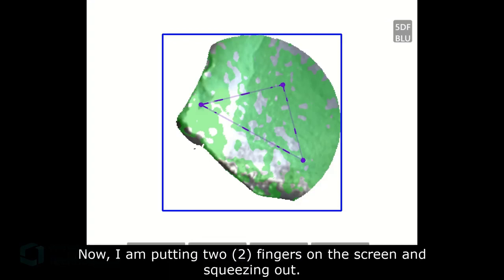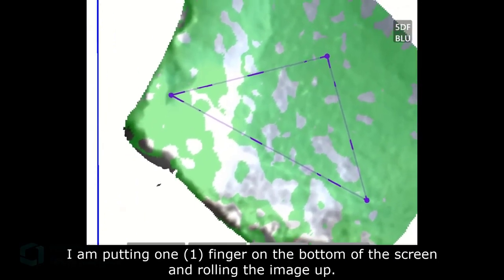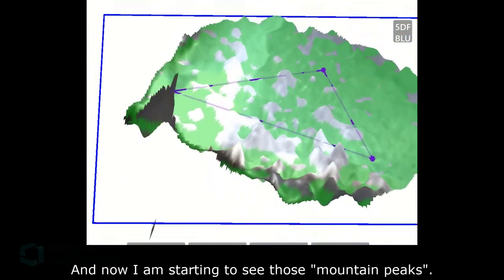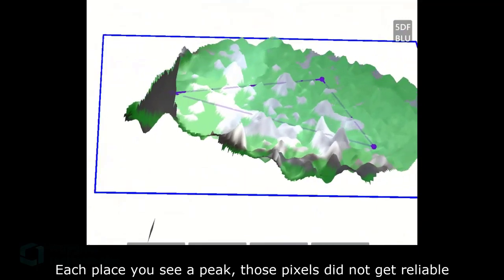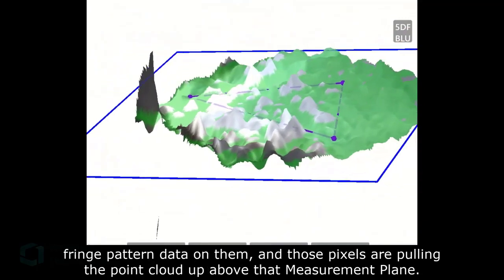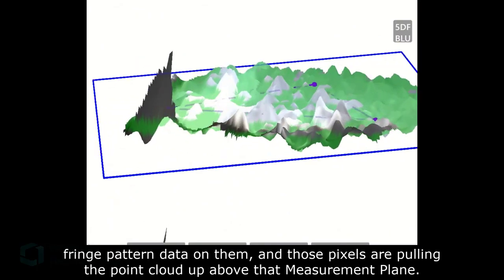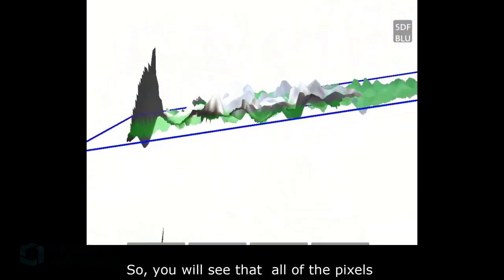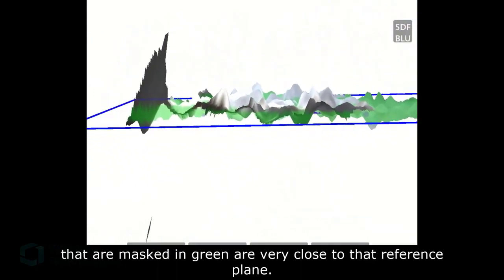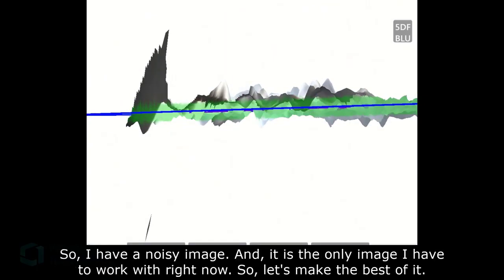Now I'm putting 2 fingers on the screen and squeezing out. I'm putting 1 finger on the bottom of the screen and rolling the image up. And now I start to see these mountain peaks. Each place you see a peak, those pixels didn't get reliable fringe pattern data on them. And those pixels are pulling the point cloud up above that measurement plane. So you'll see that all of the pixels that are masked in green are very close to that reference plane.